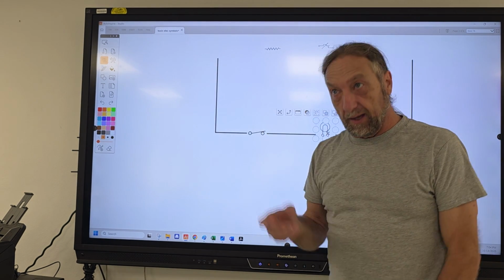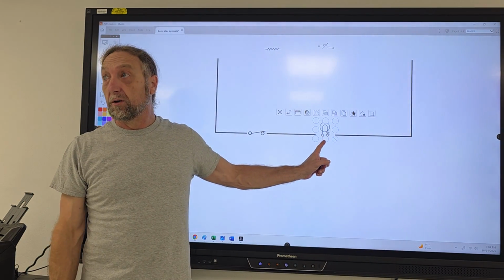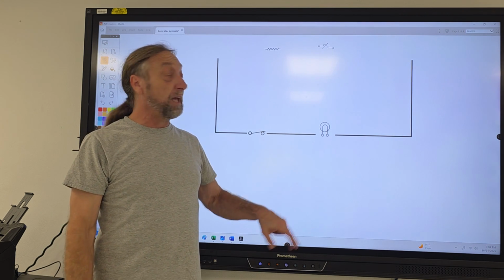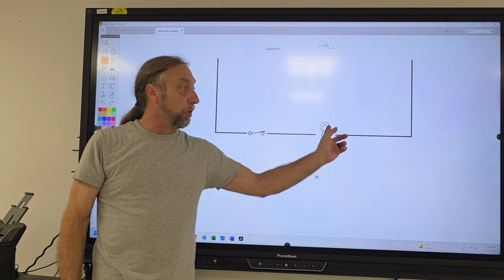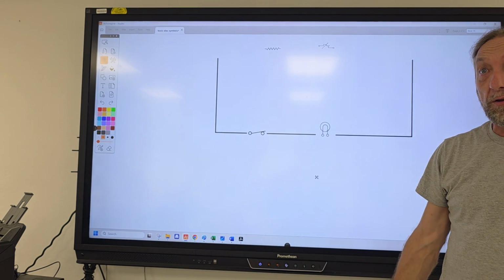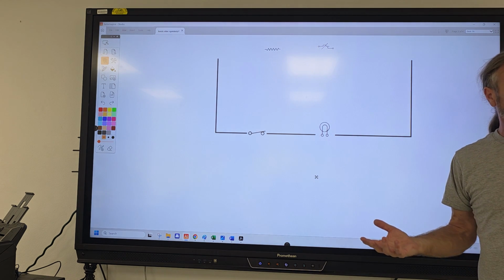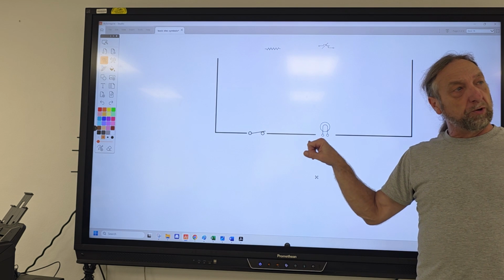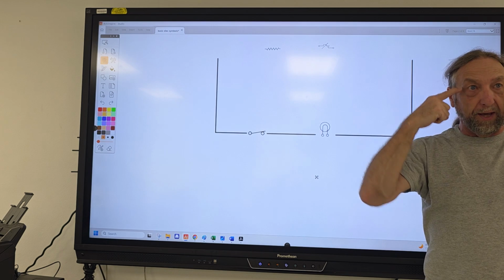So if you can safely check voltage to the load, that's the first thing you need to do. Now, that's if the machine is working, but a part of it is not working, I'm gonna go right to the load. But if the customer calls you and says, my machine's not turning on at all, well, before I take anything apart, I'm just gonna check to see if there's power in the outlet in the wall. Okay? But going back to this, troubleshooting begins with the steps of, okay, what's the complaint?